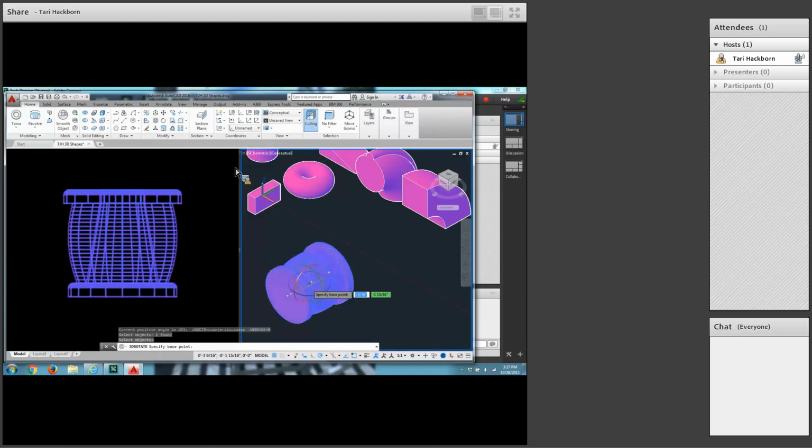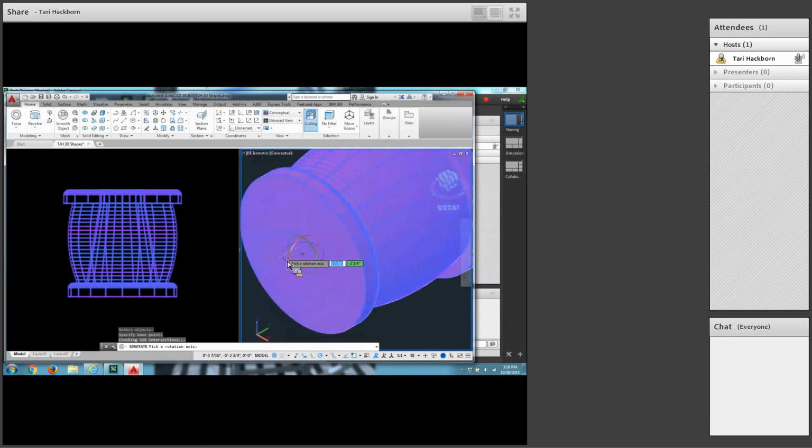As soon as you enter, this little symbol shows up right here with all these little ribbons. You want your rotation point to be at the center point of the bottom of the paper clip holder. So usually if you get near the bottom edge, the center point shows up and you can click, and that moved this symbol. I know it's kind of hard to see because this got all highlighted, but that moves the symbol to the center. Now you just pick the ribbon that's going to rotate it in the direction that you want. In this case, it's going to be the red ribbon, right? Let me just zoom in there a little bit. So I'm going to click, there, on the red ribbon. Okay. And I'm going to type 90 and enter, and that stands it up for us. Okay.